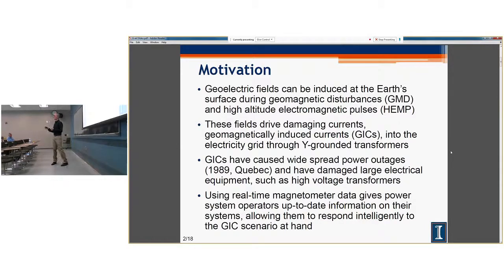So the other way is putting a low ohmic resistor in. So this makes the current not want to go into the path of the transformer. But it's important not to put a high impedance resistor in there, because then you're going to have a grounding problem with your different stations. If you have a lightning strike or something like that, you need to make sure that the zero sequence current and the unbalanced current can get out of the system. Yeah, that's a good insight, though.